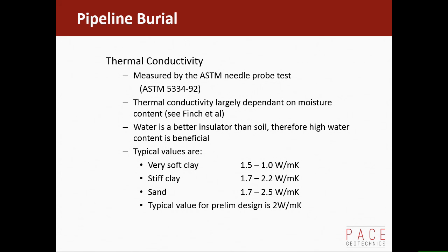Sands and stiff clays will be higher because their water content is lower, and often people use 2 watts per meter K as a first pass for design. Well, if you know your job and know the geology along your route from a pipeline route survey or desk study even, you might have a pretty good idea that it's actually lower than that.